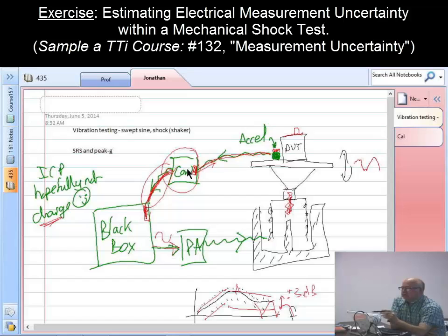So from a cable standpoint, do we have to factor in anything if it's really susceptible to noise? If you're using ICP, there's so much more error associated with the calibration and just the general noise associated with the physical test than ever you'll pick up on a cable. If you get a problem, you'll get it so loud and clear that you'll have to stop and check your connectors and such like. But if they're working correctly, and that is a big issue, by the way, if you've done vibration testing, while you connect cables together, with all the vibration going on, they often will just move a little bit or lose electronic contact. So that is an issue, but that's something you check for as part of the routine setup anyway.